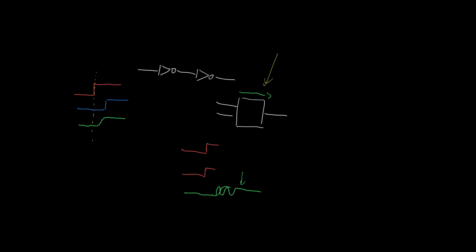And so for any logic circuit, we can give two numbers. We start the clock when the input or inputs change. The period within which the output is guaranteed not to change is called the contamination delay. Now, we can't work out the contamination delay exactly because it depends on the temperature, on the output loading and things. But if you go to a data sheet, it will give you a bound on the contamination delay. So it's a promise or a guarantee.